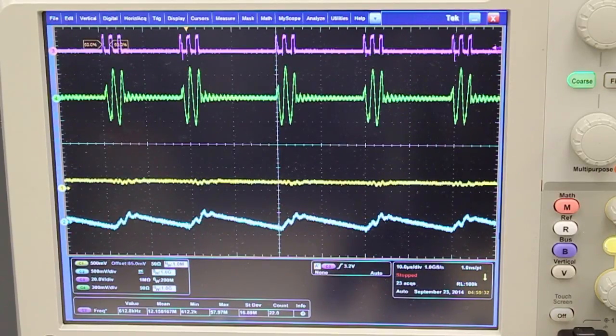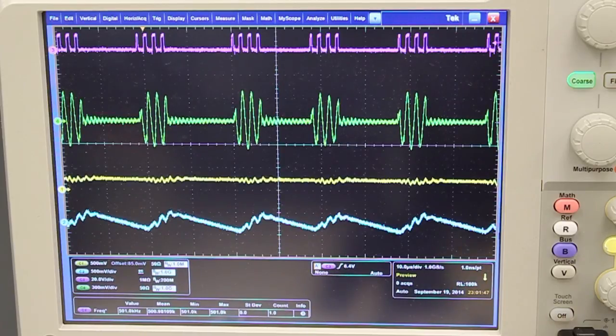This is a 5-pulse burst mode pattern under 12 ampere load. And this is a 7-pulse burst mode pattern under 17 ampere load. For all conditions, resonant current is settled to around the optimal point.